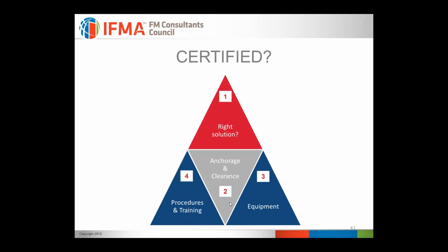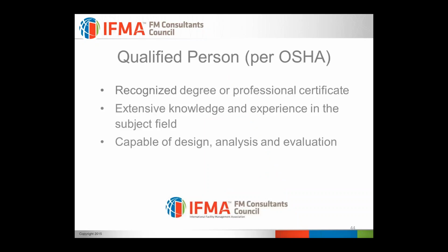And then the 4th piece of a certified system are the procedures and the training that the people who are going to be using the system need to have. And so all of these 4 components really make up a certified system, right? So don't be confused by certified equipment and think that you've got therefore a certified fall protection system, because you might very well only have one little piece of the puzzle.